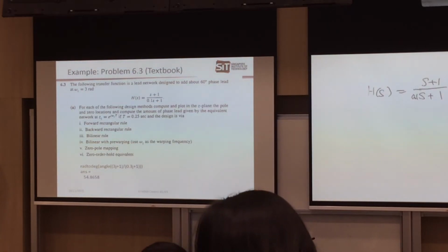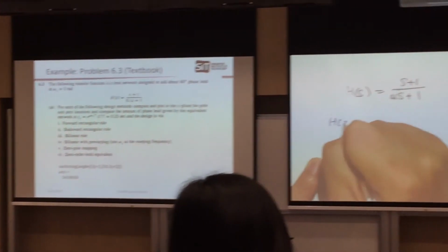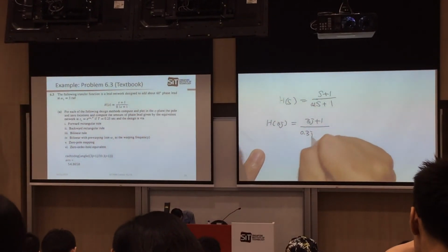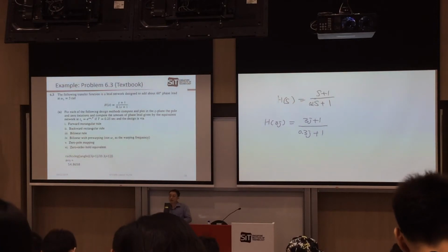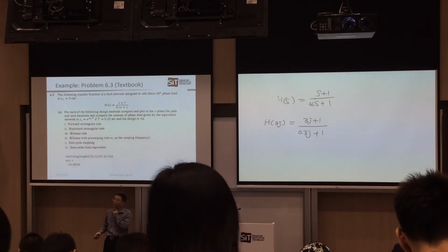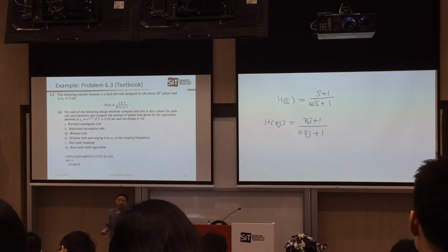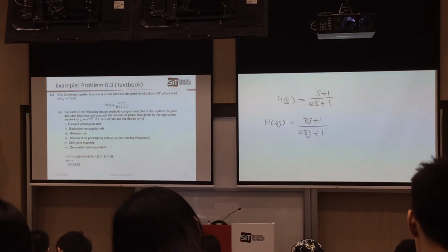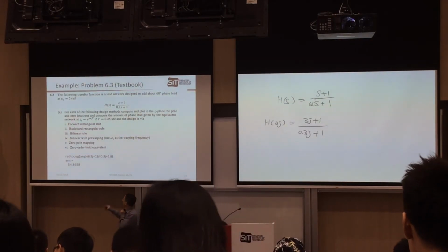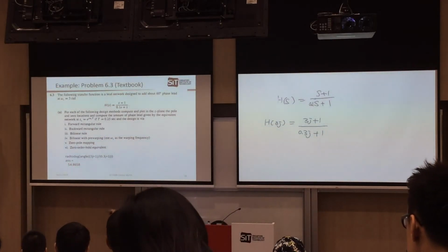So if we do the analysis in the continuous domain, then this will be a complex number, right, of your H(j omega). For this one, you run MATLAB or use your calculator to calculate the phase angle, and it's very simple, right? Basically, you find the angle of the complex number. For this complex number, the phase angle is about 54.86.